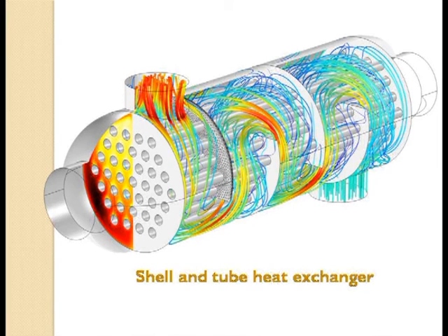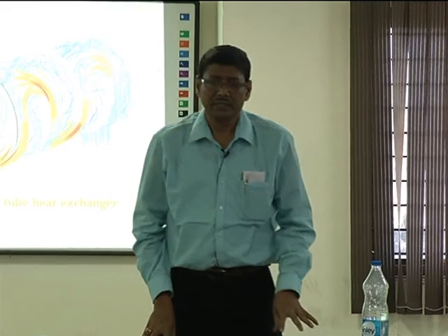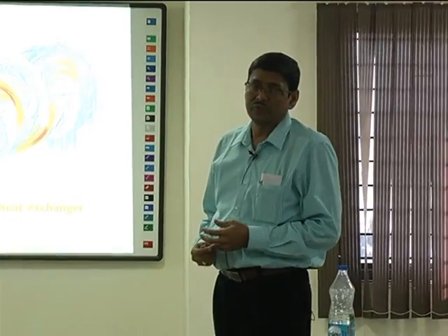As you know, turbulence will help in heat transfer. So with good turbulence, this other liquid will come out in the other direction, and while this tube will get heat transfer, it exchanges heat with this other fluid. Okay, so this is a shell and tube heat exchanger. It is not compact at all, but it is used in ground installations, large plants where a large amount of fluid has to be handled.